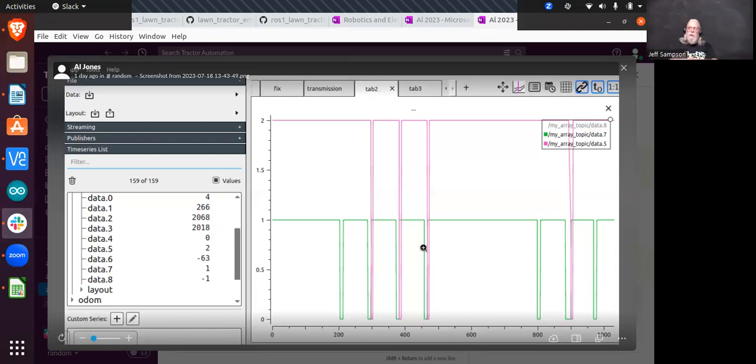One thing you could do, because of the stuff you pointed to before, it looks like you're just looking at the time. Say, if I haven't got a message for 1 second, then you declare it to be a problem. But you don't seem to be printing out the number you did get. One of the things I would do is go in there, and at the point it says I just had a problem, print the numbers out as the thing runs. Is it actually 1001, or is it like 5,000 or something? Is it just right on the edge of not working, or is it something blatantly wrong? If there's something blatantly wrong, you probably have something wrong in the code, or it's the way you're interpreting the radio stuff.